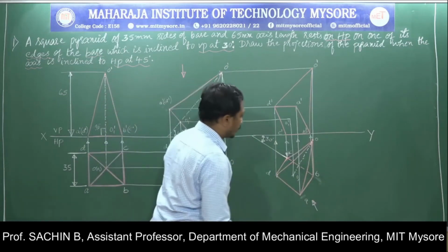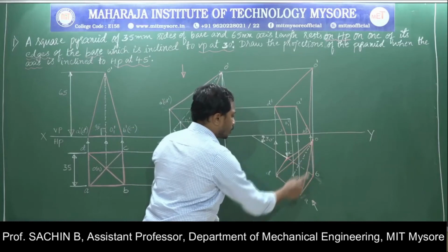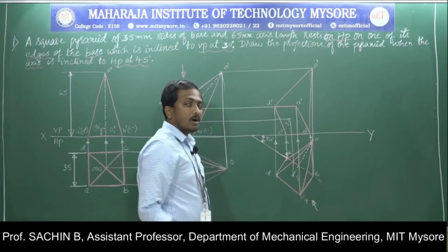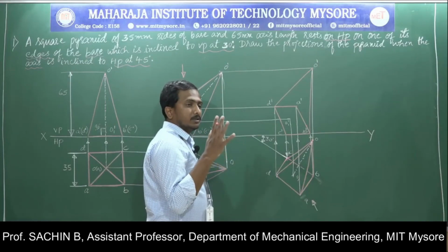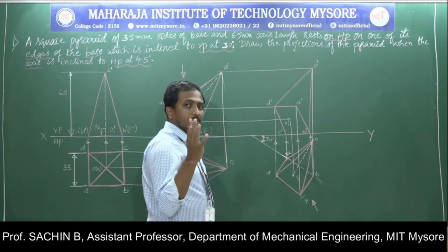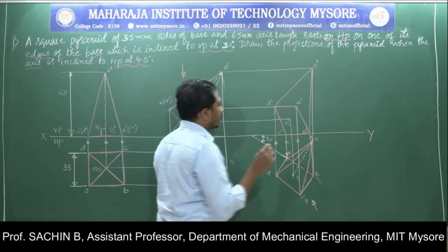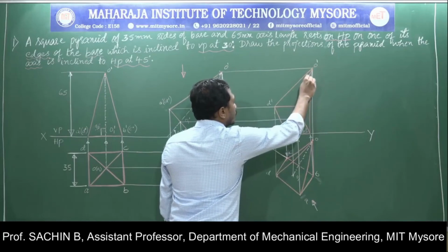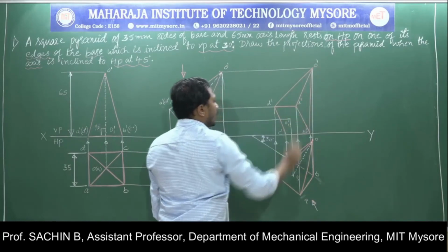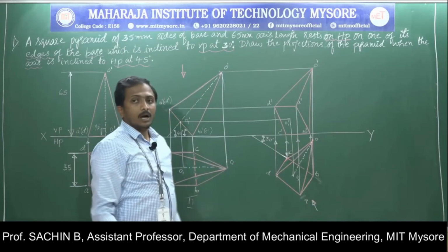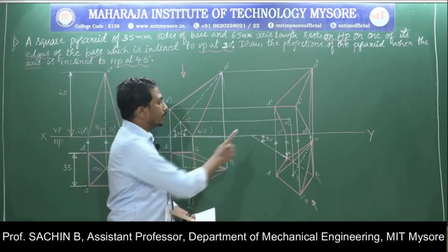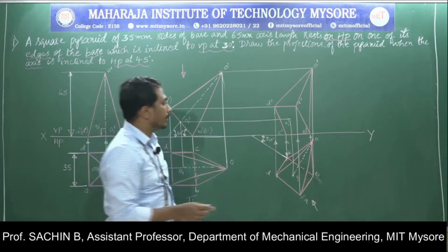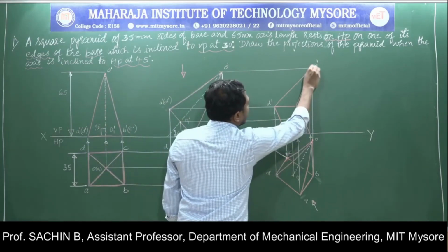And one more thing about the observer, O to A and O to base are near to the observer according to the second concept. Means the edges that are near to the observer are clearly visible. Means O to B already is visible, O to A is one more edge that is clearly visible according to the second concept. And one more edge that is completely left, that is the hidden edge or the invisible edge, that will be indicated with the dotted line.